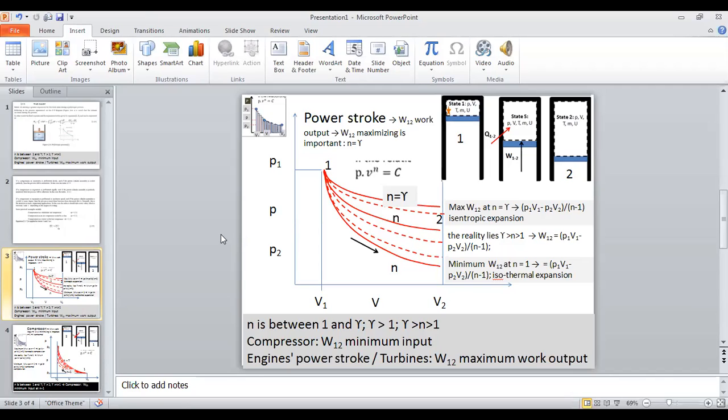The energy from the combustion should not be released as heat loss, and it should purely do work, with friction negligible. Practically this is very important to get the maximum possible work done with minimum possible loss of thermal energy availability. That's what we call isentropic.